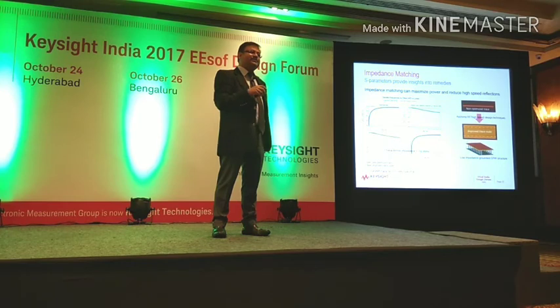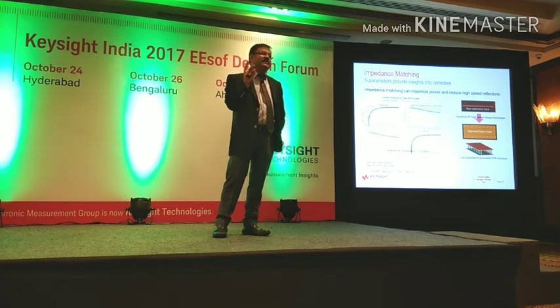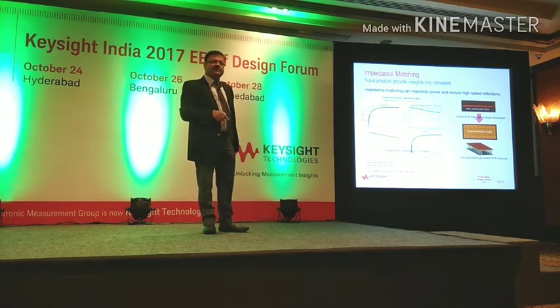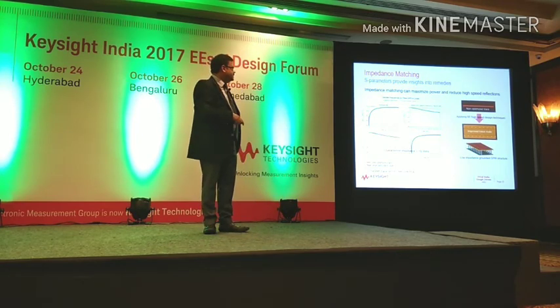Were you aware of touchstone files? Probably very few SI engineers were aware of the S11 and S22 concept. Everybody was behind TDR. The whole science was about TDR. Now everybody is talking about S-parameters, S11, S22, S21. Something similar is going on in the power electronics industry. So you optimize the whole thing.